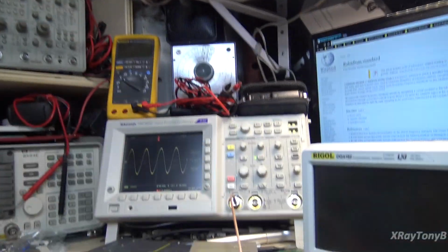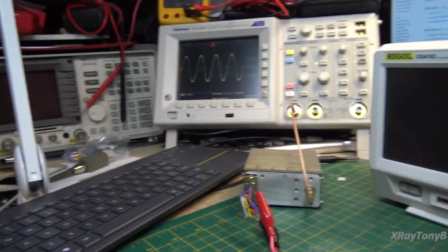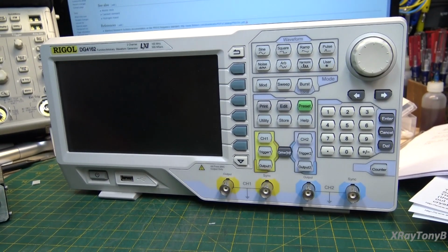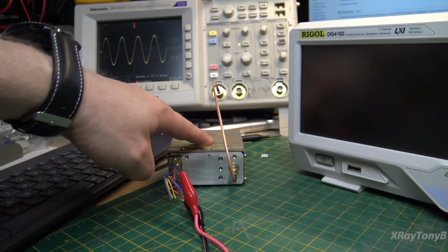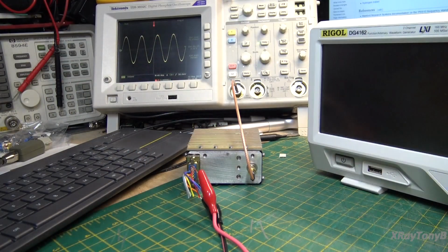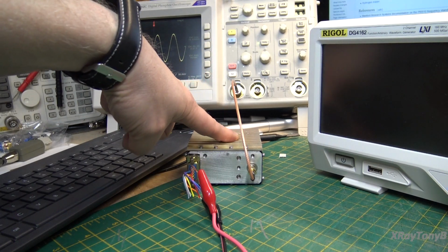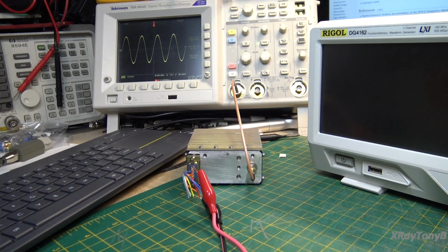What's more, if you look at, for instance, the spectrum analyzer that I have, it has a 10 megahertz input. A lot of these RF generators and oscilloscopes and so forth, if you go to the rear of the scope and the rear of the test equipment, they have a 10 megahertz reference input. If I were to split that 10 megahertz reference off and feed it into all of these devices, all of them would sync to this one very accurate reference. Not only would it make those devices very accurate, but it would also synchronize them to one another, so my test results would be very, very accurate. Okay, that's the point of this.